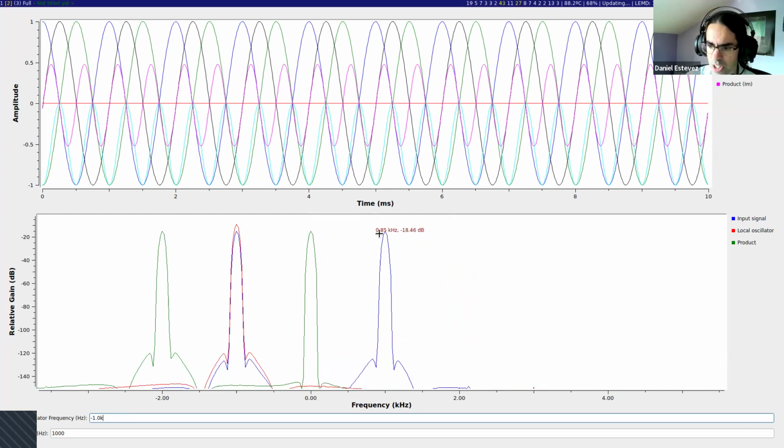So that's the proper sideband. That is how they are called: positive sideband, negative sideband, that we want to translate to 0. If we had translated this one, then if we have something of less negative frequency, it's on the right, and now it has slightly positive frequency, so that's confusing. That's the reason to prefer translating this one.